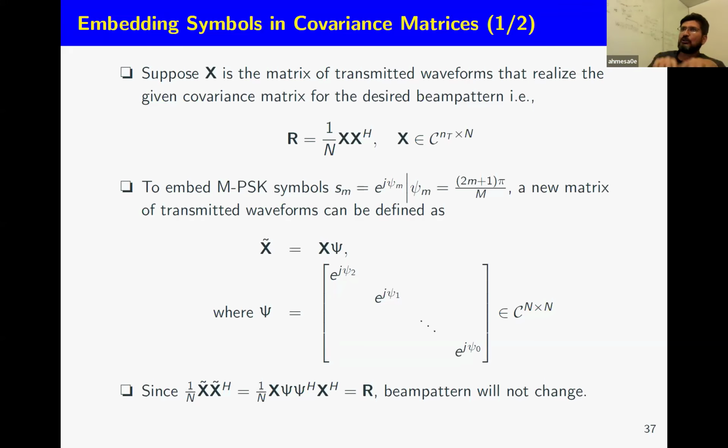In our case, we know what we have transmitted and what the correlation was between different waveforms. So we compare those cross correlations with the received waveform against the transmitted waveform. If the cross correlation matches, then we suppress. If there is no correlation between the transmitted and received waveform, we can perfectly jam them.